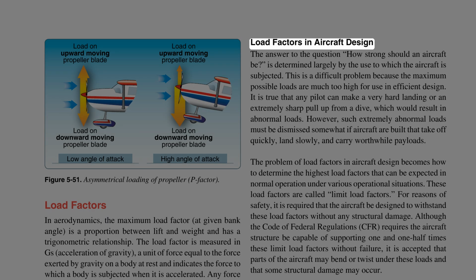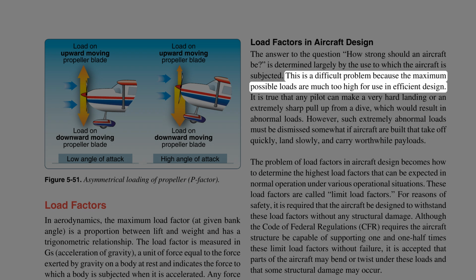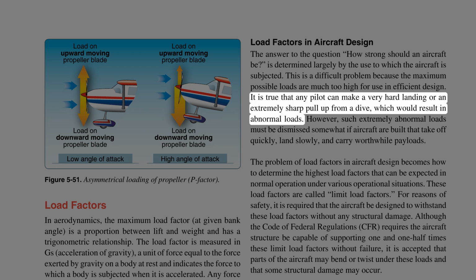Load factors in aircraft design. The answer to the question, how strong should an aircraft be, is determined largely by the use to which the aircraft is subjected. This is a difficult problem because the maximum possible loads are much too high for use in efficient design. It is true that any pilot can make a very hard landing or an extremely sharp pull-up from a dive, which would result in abnormal loads.